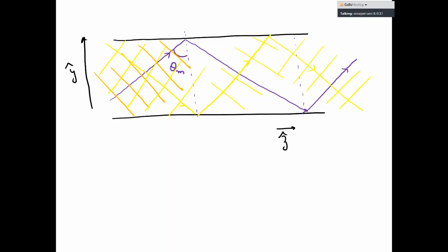Now for this plane wave to exist and remain a plane wave, over here I have a term like that, and then when it turns around, I still have to have a plane wave. So there has to be a certain phase which has to be met, otherwise the plane wave approximation would be broken. And because of that phase which has to be met, we get discretized solutions. Only certain angles would support that the phase is maintained when the reflection happens, and thus it maintains the plane wave nature of the wave. Only certain angles would allow that, and thus we start seeing discretization of the modes.